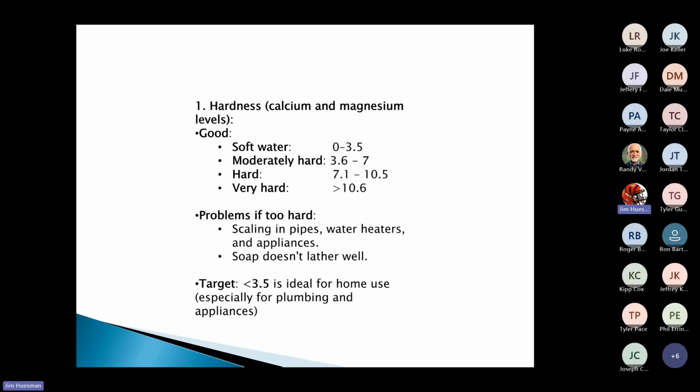All that hardness sticks to the pipes and to our heat exchangers, and even to something as simple as a solenoid valve on your wash machine. Or if you're dealing with a commercial, maybe you're dealing with a massive heat exchanger, and scale will destroy it.